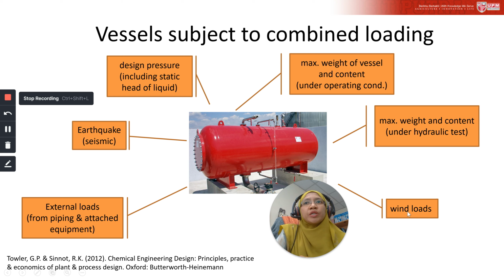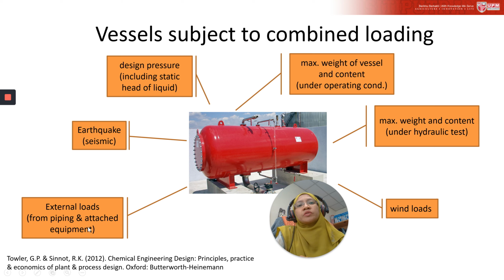We have wind loads, design pressure including the static head of liquid, earthquake or seismic loads, and external loads imposed by piping, attachments and other equipment.